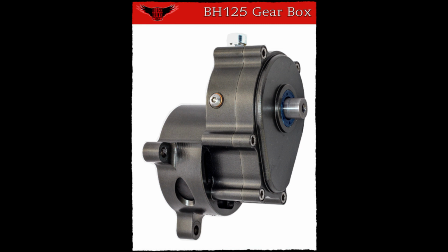Some examples are a 2-stroke RPM reduction from 6,500 engine RPM with a 3.47 to 1 reduction, resulting in 1,873 propeller RPM. A 4-stroke RPM reduction could be from 5,500 engine RPM with a 2.43 to 1 reduction, resulting in 2,263 propeller RPM. A gearbox is a simple device that bolts directly to the engine and, in turn, has the propeller bolted directly to it.